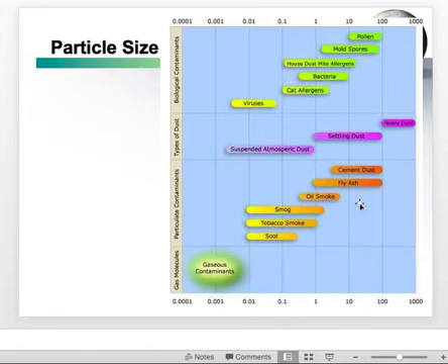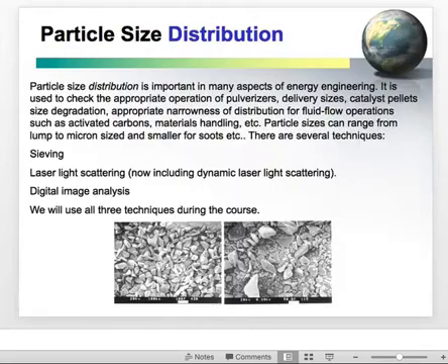Should have the units and of course be labeled. These have this interesting behavior of being suspended and then slowly settling out, and so they can be in the atmosphere for a long time, particularly as you get smaller and smaller. So other dust, smoke, smog, soot, these are all interesting. They're all going to have a range of particle sizes, and essentially that distribution is one of the critical pieces. And so you'll see that I often stress distribution in the terminology. So this is not something where you can do particle size with a mean and a standard deviation, because it does not work that way.